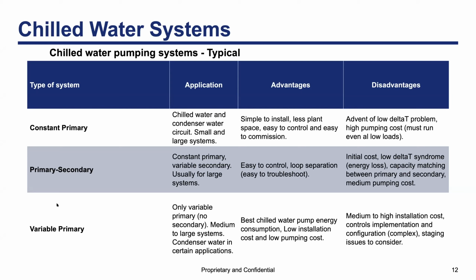In between these loops, there is a bridge, also called a hydraulic decoupler, and it is used to balance the thermal energy between the primary and secondary loops. The water can flow in either direction within the bridge, from primary to secondary and vice versa. And this depends on which flow is greater at any given point in time and depending upon the load of the building. The intent with this system is to isolate the control of the chillers from the coils.